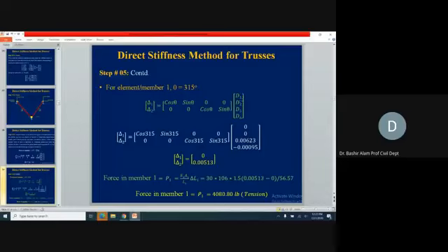What was the displacement at the starting end? Those were d1 and d2. This is the near end, so dnx, dny. So we are putting the actual displacements d1 and d2. And at the far end, if you remember, joint 3 was the far end. There the displacements were 5 and 6. So we are putting d5 and d6 for that particular member.